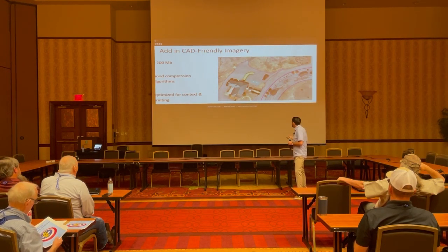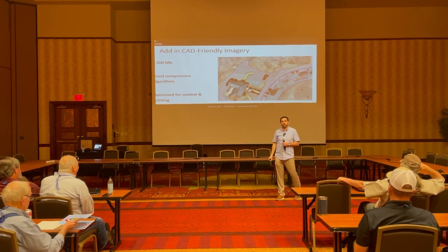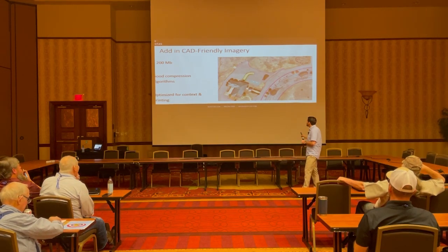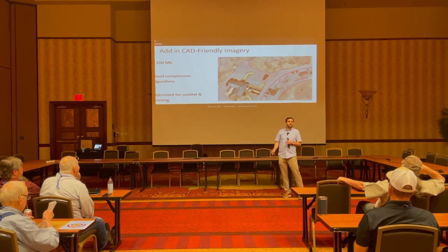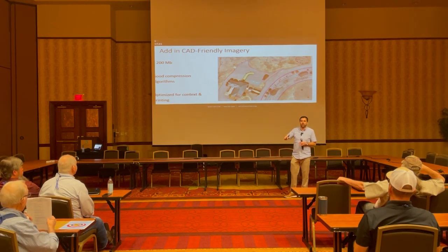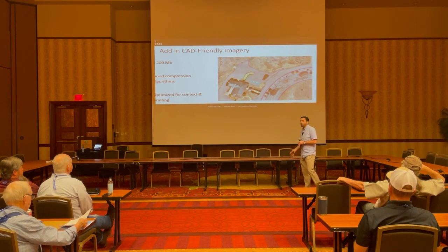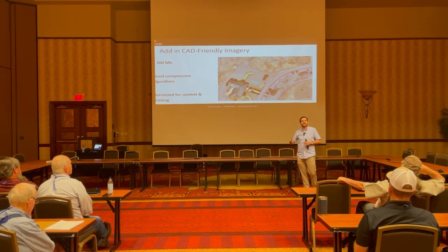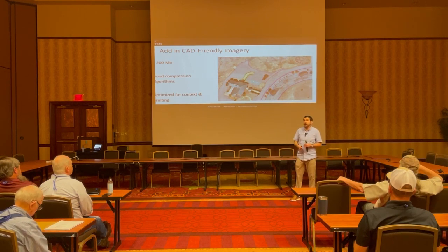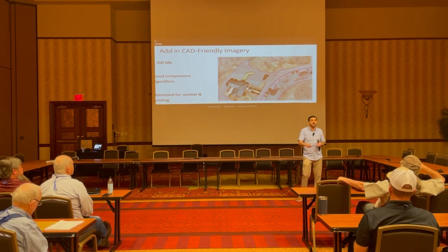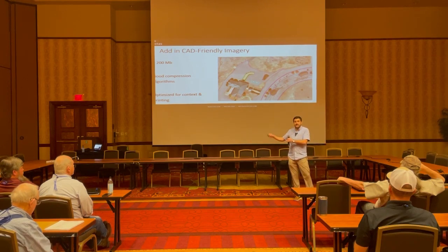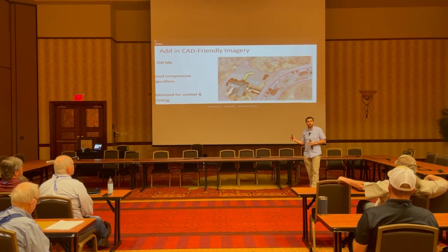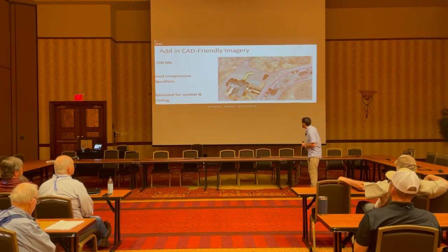When you get it into CAD, there are a lot of really cool compression algorithms out there, whether it's ECW or MrSID or something like that, that can actually compress it so that it's less than 200 megabytes, which is usually about the Goldilocks limit for CAD we've found. Oftentimes smaller if we can get away with it, but trying to get it so that it's great for context and visibility, but still a small enough size that it's reasonable to deal with, that you can share it with someone else, and that you don't need an insane workstation just to open the file. Having that hugely improves usability of the final product.